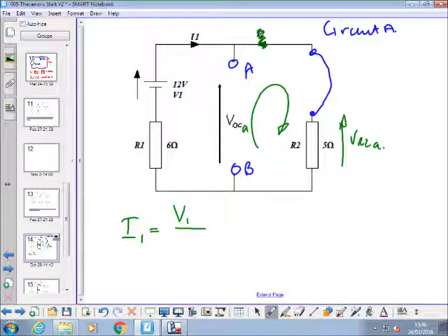How much current is flowing down that middle leg? None. So all the current is going round the outside and through those two resistors in series. I know they're in a strange place. We've normally put them on the top. It confused you a bit last week, Carl, didn't it? But that is a series circuit all the way round the outside, so it's going to be R1 plus R2.